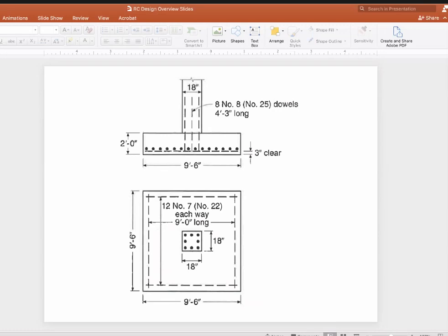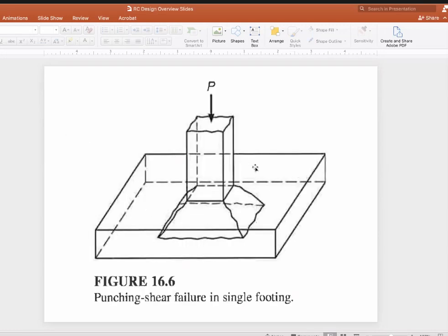And the shear is speaking much more generally about the entire section being failed and the entire column going through the pad of the footing, and a complete structural failure through the entire depth. That would be the key. So there could be a chance of, if this is off near the edge, it crumbling and so on. And there is a check in place for that sort of thing. I hope that helps. Other questions?